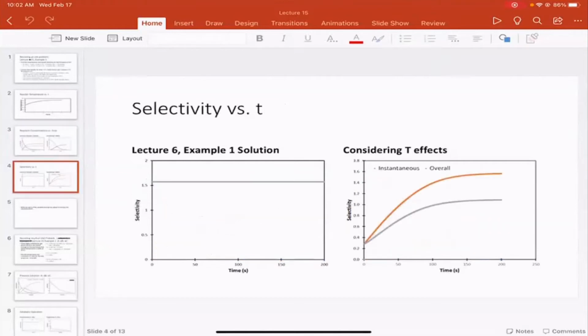But in this batch reactor, where we started at room temperature, which quite frankly, unless you're going to preheat the reactants separately and then add them to the vessel, is very representative of reality, where you would start the reactor at a lower temperature initially, and then allow the jacket and the heat of reaction to contribute to, assuming of course that it's exothermic, heating up the vessel over time, or to heat the reactants over time.